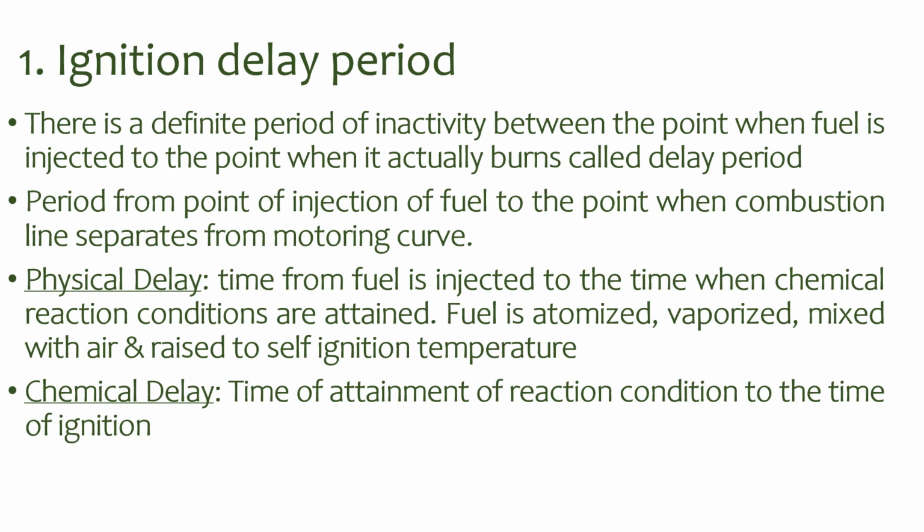The delay period consists of physical delay as well as chemical delay. The time from when fuel is injected to the time when chemical reaction conditions are attained is called physical delay, in which the fuel is getting atomized, vaporized, mixed with air and raised to the self-ignition temperature. Chemical delay is the time from attainment of reaction condition to the time of ignition.